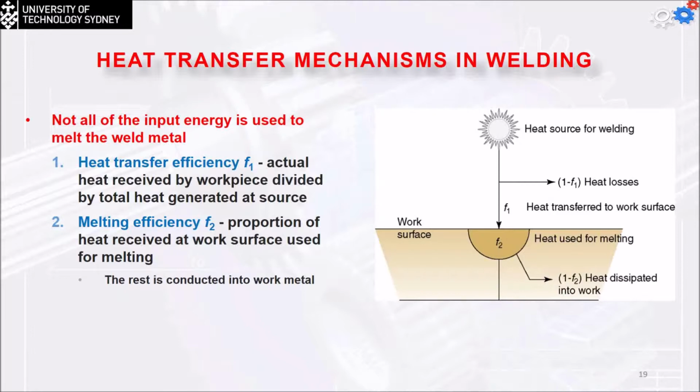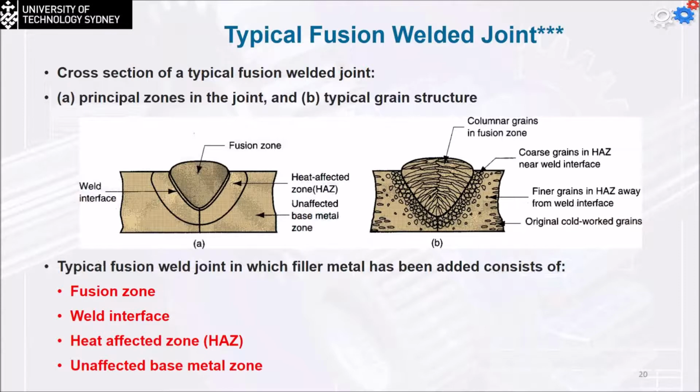The microstructural shape of the material is going to look like the following. This part was a melted pool which has been solidified. That's why you can see that the microstructure is going to be a big one. It's usually columnar grains in the fusion zone of the weld.